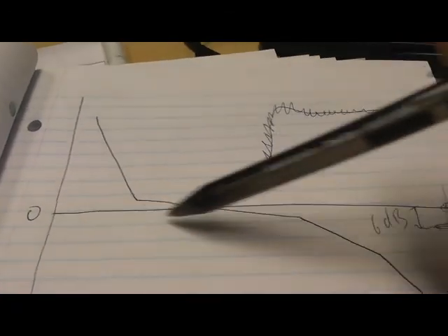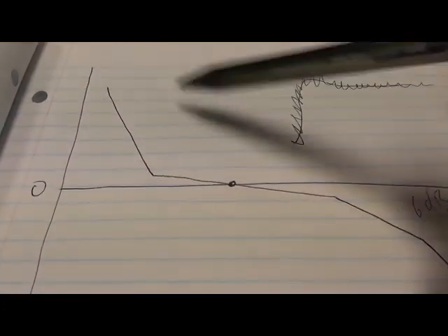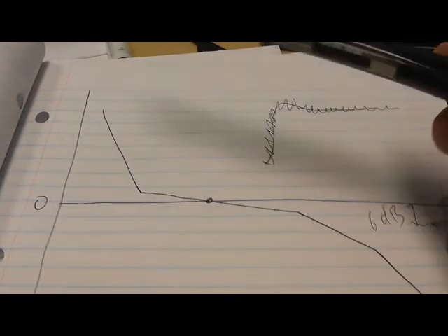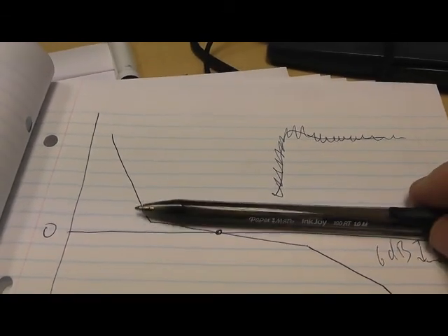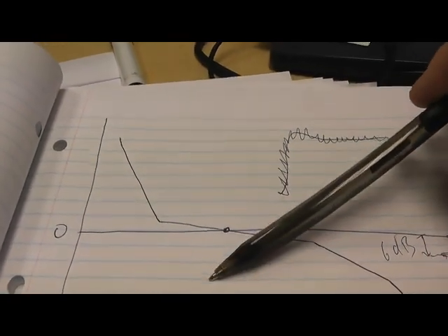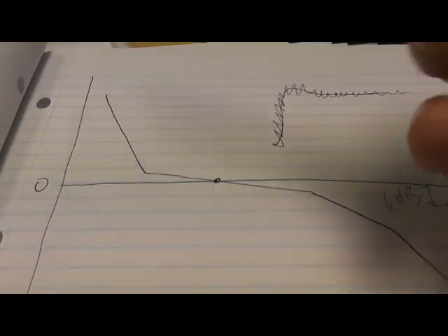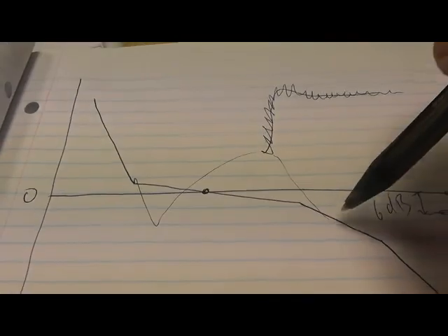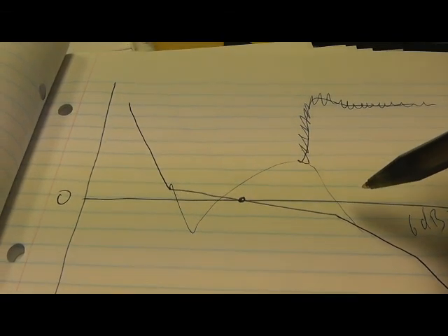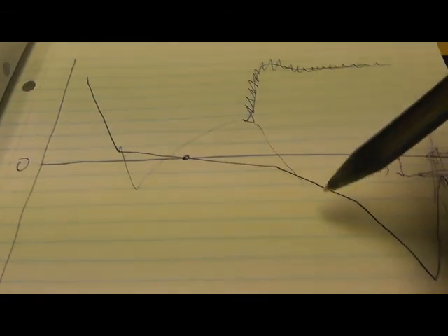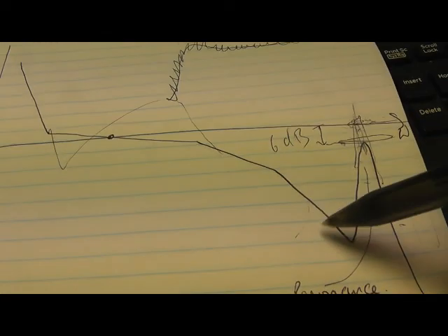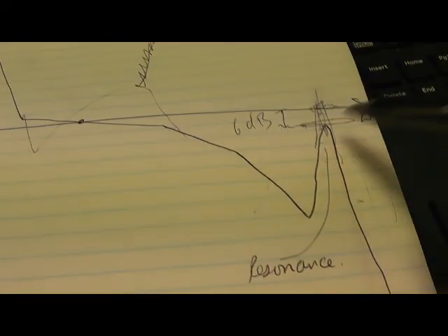But if we keep the bode plot looking something like that, and with a steep response slope at low frequencies, going through about -20 or even flat, certainly not at plus. Once you start going through with a positive slope, you will end up with multiple crossings of the 0 dB, and you have multiple phase margins, and that can lead to interesting effects as well. Anyway, so yes, you want to do that, and then roll off at high frequencies to attenuate any resonances or noise there.